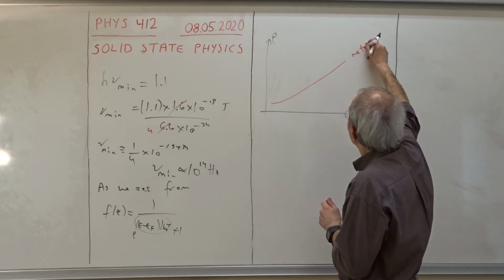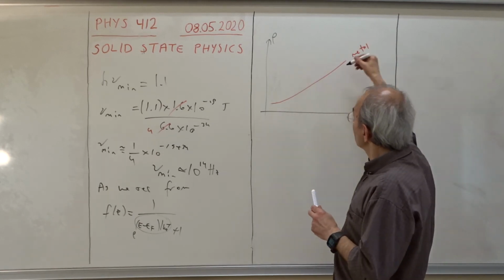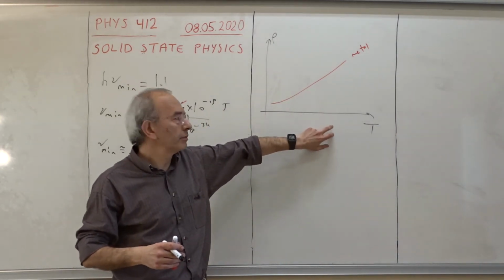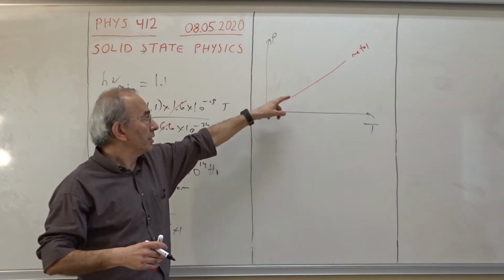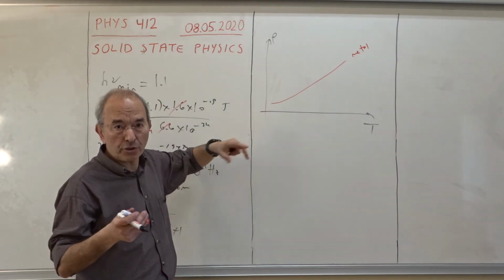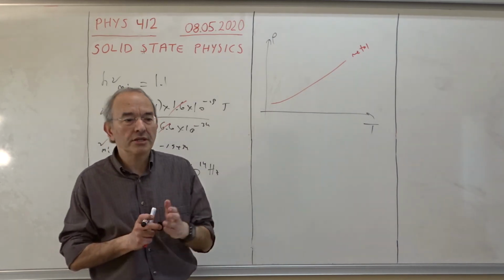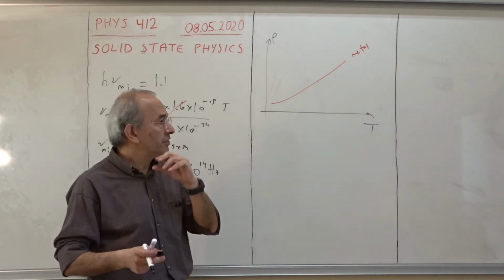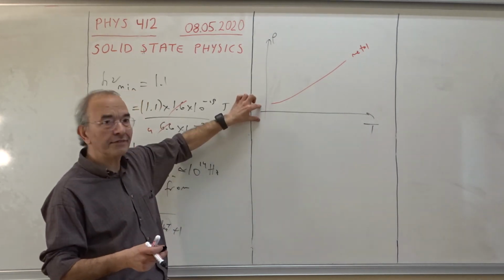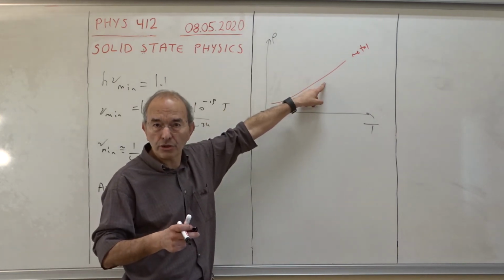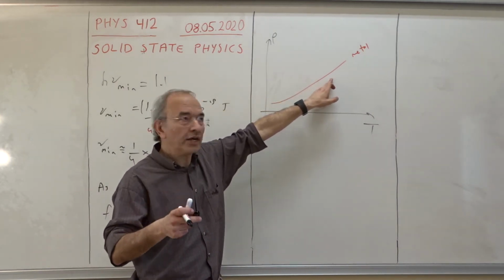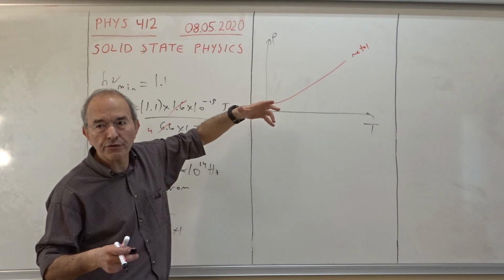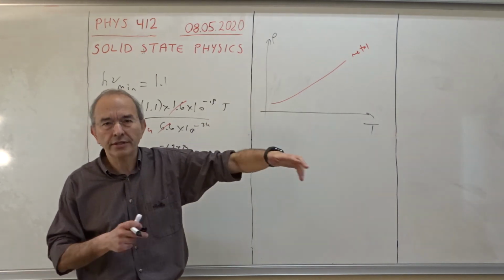This is the case of the metal. Resistivity was almost linear, including room temperature here, but it doesn't pass through the origin, as I said before, because of some unwanted impurities, dislocations in the system, etc. Necessarily, there is some residual resistivity even at 0 Kelvin, so this line, this linear function, doesn't pass through the origin because of the presence of some unwanted impurities, other atoms, etc.